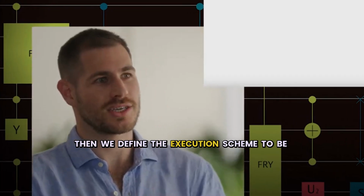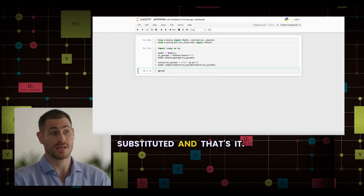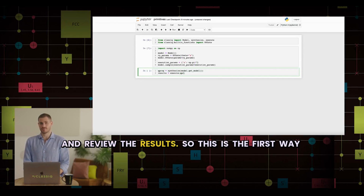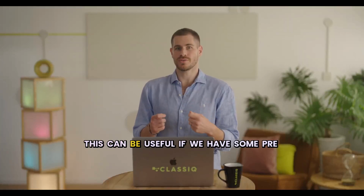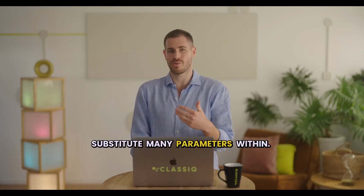Then, we define the execution scheme to be sample, as usual, but now we pass to the model the execution parameters to be substituted. And that's it. Now we can continue as usual and synthesize the model, and even execute it and review the results. So this is the first way to pass parameters into the model. This can be useful if we have some pre-processing to do, some intermediate calculations, or a loop where we want to substitute many parameters within.